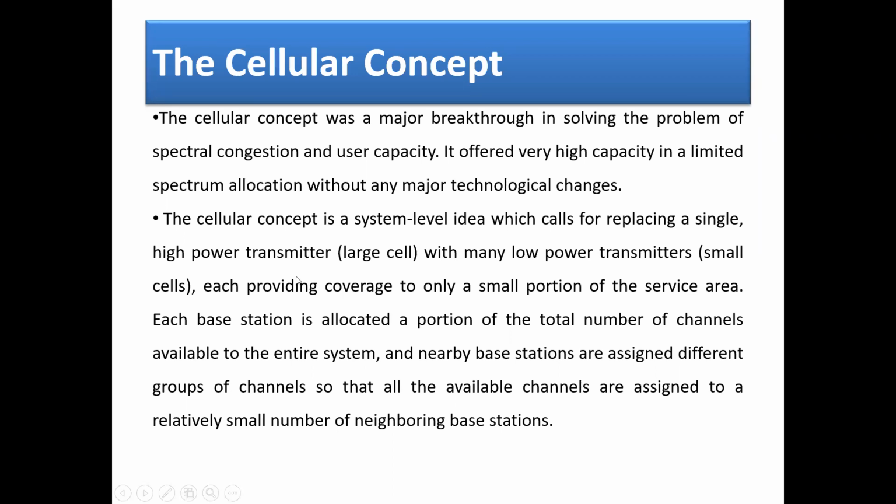Now, the cellular concept is a system level idea, which calls for replacing, this is the important point, a high power transmitter, or large cell, with many low power transmitters, small cells. At the beginning, we have what? We have only a single cell. So at that time, we have high towers with a high amount of power transmitted.